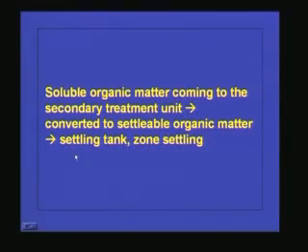And we have already seen that the secondary sedimentation tank has to be designed based upon zone settling because the particles are flocculent in nature and it is a concentrated suspension. A concentrated suspension with flocculent particles comes under zone settling, and towards the bottom of the sedimentation tank the concentration of the particles is so high that there we will be experiencing compression settling.